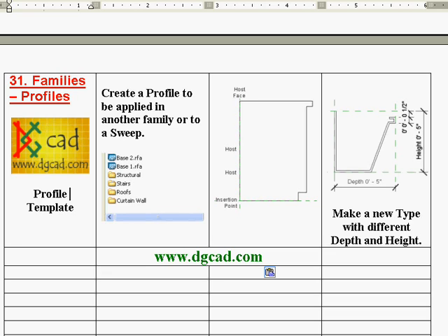A very basic kitchen counter, where you don't care about the detail of the cupboards. You just want to get the mass shape in there and extrude it along the wall. And here we have just a rain gutter that sits at our roof, and we can tell how that one goes. We'll go in and have a look at that because we'll create a new type based on a 5x5. We'll maybe change sizes and make a new type for this family type.